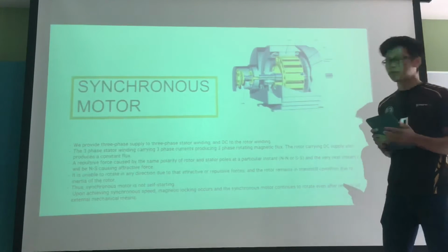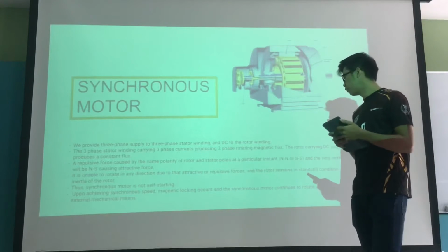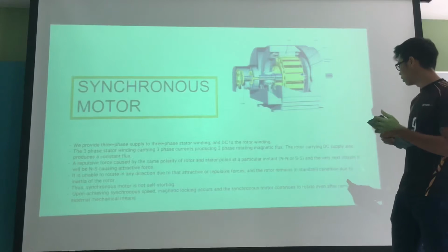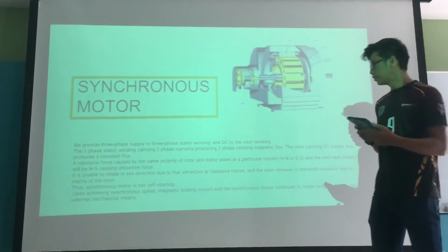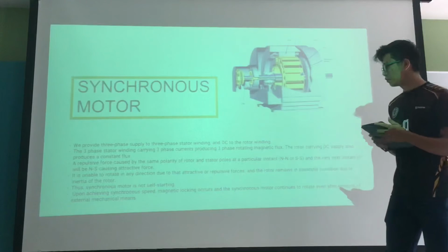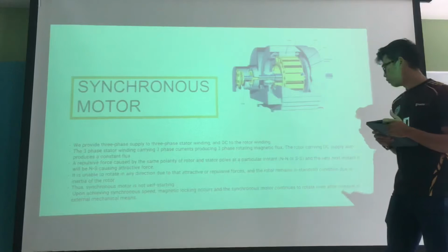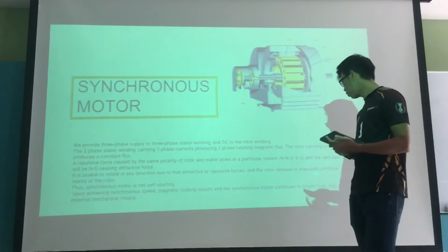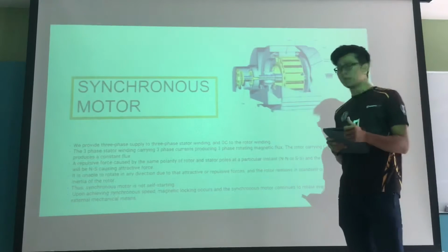The rotor is unable to rotate in any direction due to those attractive or repulsive forces, and it remains in a standstill condition due to the inertia of the rotor. Thus, synchronous motor is not self-starting. Upon achieving synchronous speed, magnetic locking occurs and the synchronous motor continues to rotate even after the removal of external mechanical means.